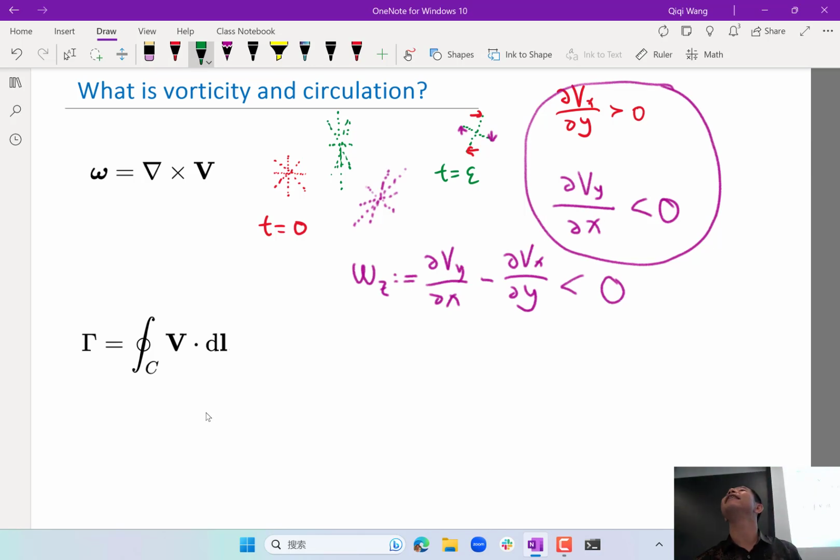Yes. For the purple case that we were showing before, does that necessitate that there's zero vorticity, or just that there might be other factors that would possibly tell this? Yes. So in the case where there are two rotations, that's what you mean, right? If the angle of the two rotations are exactly the same, that means there is no vorticity. But if the angles of the rotation are different, then there is going to be vorticity.